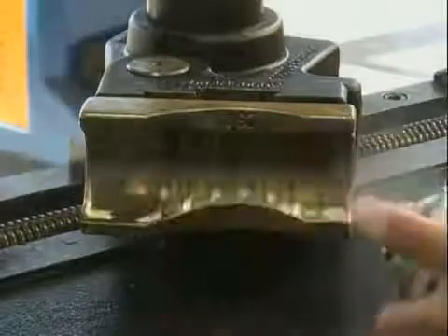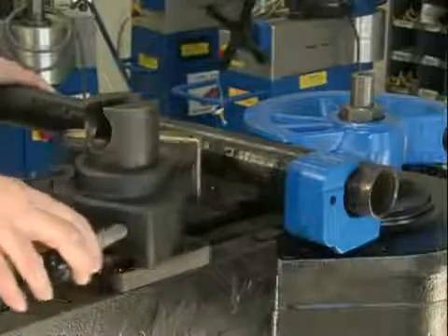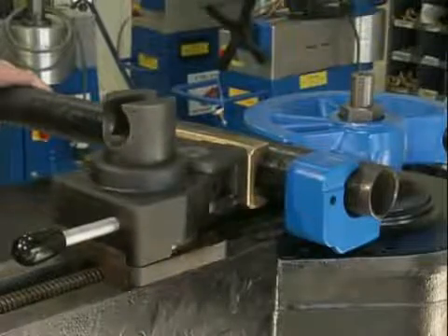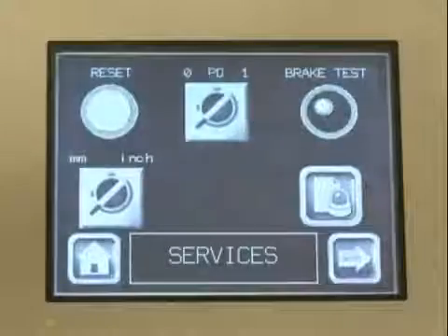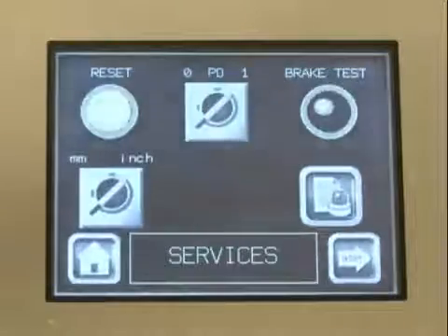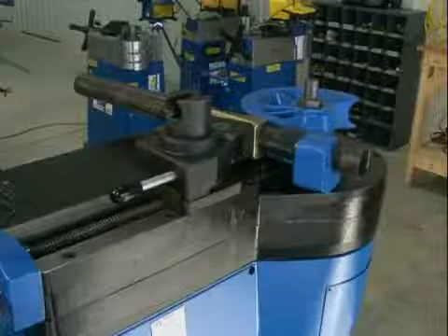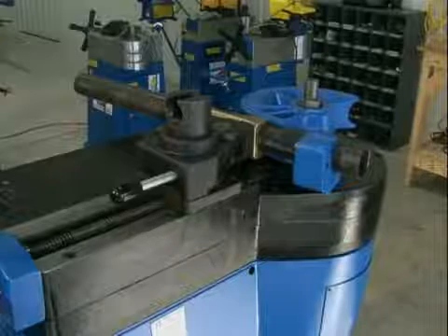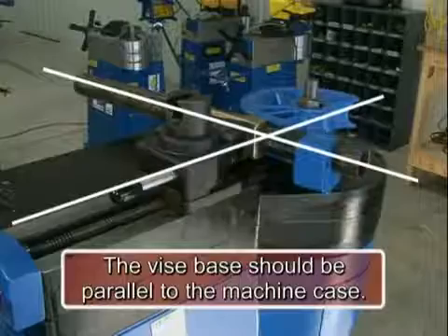Lubricate the face of the counterbend die with Ercolina spray grease before inserting the workpiece. Using the handle provided, move the counterbend axis to securely position the material between the counterbend die and the center former. If the pressure monitoring is turned on, the pressure die axis will need to be reset by depressing the icon. Proper vise tension will allow the vise to pivot in and out of position as needed.